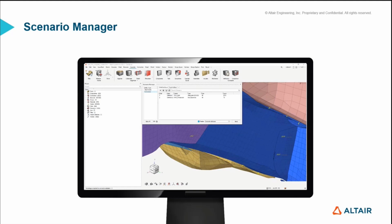So with the improvements that came in 2022.1 with the metadata mapping from the parts and from the CAD assembly, it means that effectively, if your incoming CAD represents your connectors and that contains metadata on the part level, we can map that part level to the connector. We can independently have controls on how the customers want to model their connectors, and then using Scenario Manager, we can robustly apply those controls to those connectors via that metadata that comes from the part. So this really is a way of bringing all of that information together and making sure you get the right realization on the right connector at the right time.